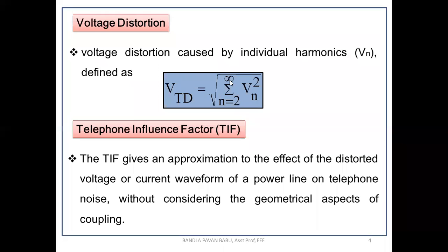So if we consider the power quality analyzer, it is a kit we use to measure the harmonic components also. With that we can measure up to 40 to 50 harmonics. If the order is 3, 5, 7 and so on, and if I start from 3, up to 40 harmonics it can measure the magnitude and the time period. So with that harmonic, what is the change in the voltage and what is the total harmonic distortion, everything we can get.